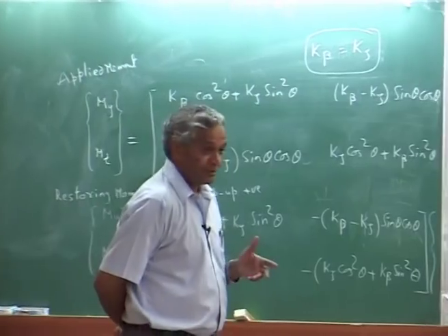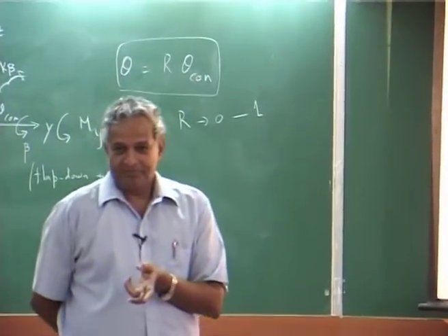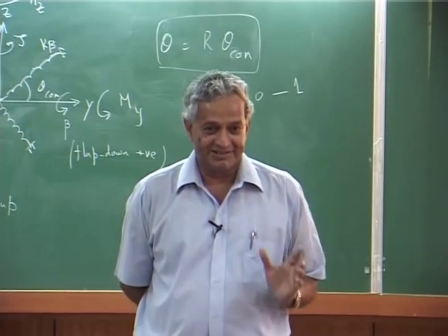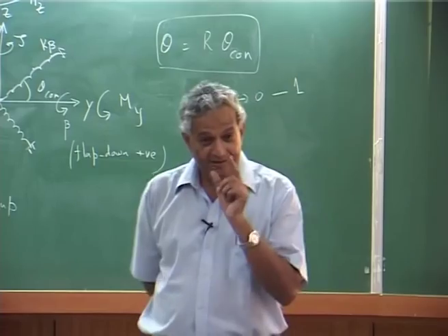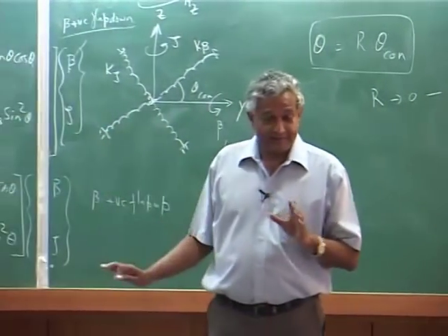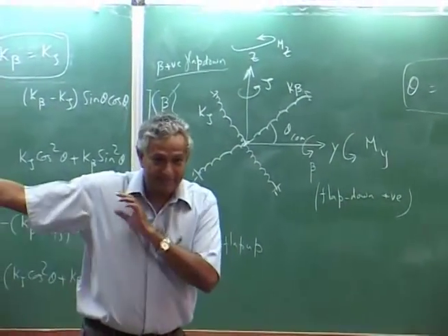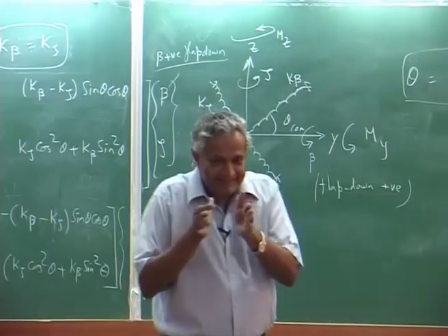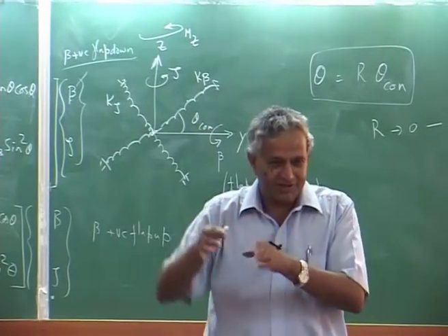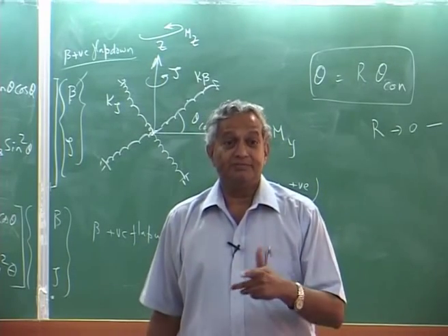Whether you can design a blade like this is called matched stiffness blade configuration. But please understand I am deriving all these things with this type of idealized model. For an elastic blade you have to see at the junction where the stiffness is there, where it is the flexure, whether you can get matched stiffness.